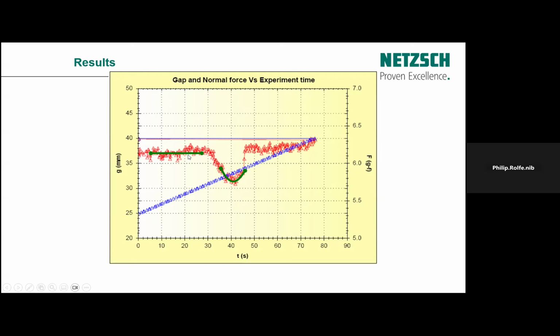The software will actually, obviously these are really small normal force measurements. If you look on the right-hand side, it's very sensitive. So what we're going to do is average the normal force for the first 15 or 20 seconds, and that would be our mean value of the weight of the ring. Then we fit a second order polynomial to this and see what the minimum is, and that will give the weight lifted. And so we can do the calculation from that. So it's easy to do.